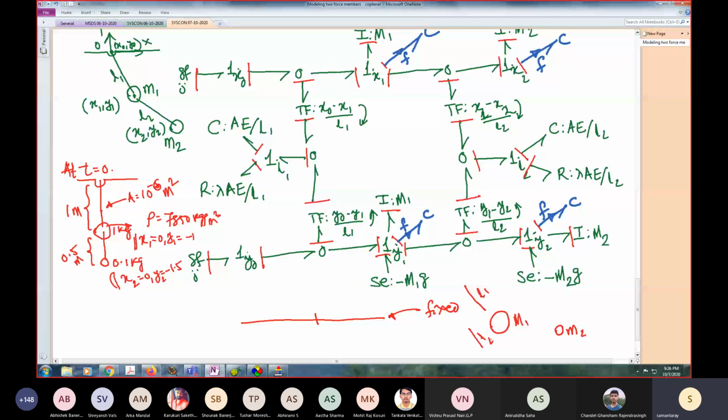Now these objects' coordinates are given with respect to the inertial frame. So this line will be drawn between two coordinates. Those coordinates are measured from the origin. I will basically put that line as a point, so that when this point moves according to x1, y1 and this point moves according to x2, y2, that line will be automatically created. So I need this. In addition, I have put some tracer. What is that tracer? You will see. The object will move, right? That tracer actually will leave a point behind, where that object was previously.